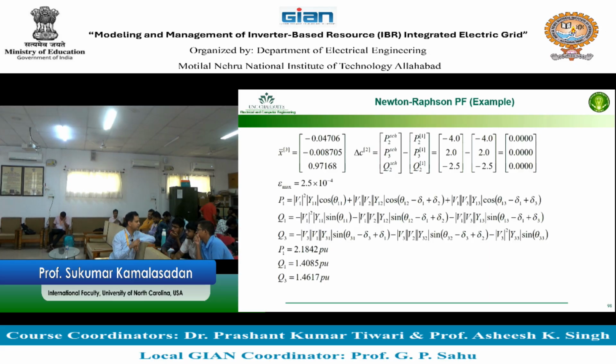So what you do is you look at what is the power from the grid. The substation bus is the grid. So the power on the substation bus is the power from the grid. So the cost of this model is: minimize the substation bus power, so minimize the summation of PG plus jQG for a specific time, whatever the time. So how do you minimize the power?